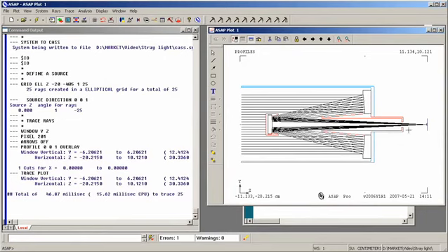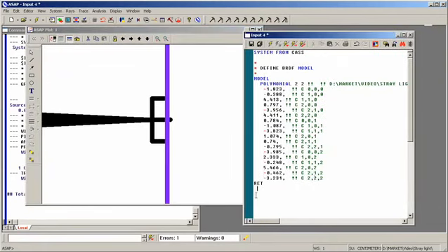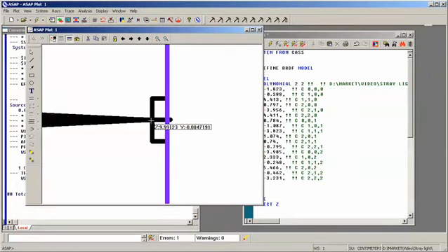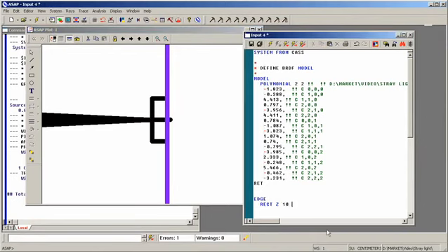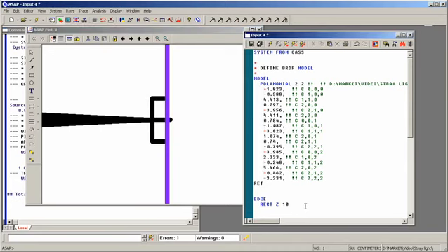Here's the geometry we had before. We want to scatter rays from the interior of the inter-conical baffle to the detector. This is the detector back here. To do that, we have to define an edge. This edge is going to be entered here. Rectangle Z. What Z value shall I use? The detector, by placing the cursor on the detector and holding the shift key down, is at Z equal 10. And the semi-diameter of the detector is about 0.15 in both X and Y.